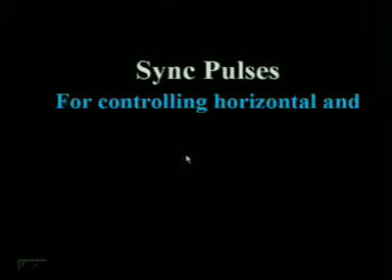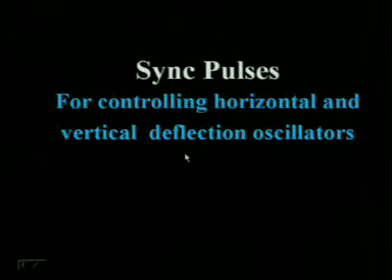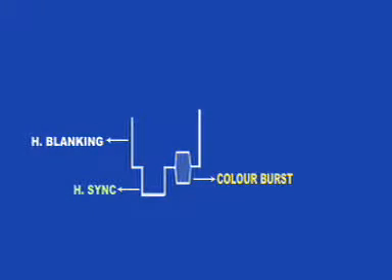Let us see here the sync pulse. Sync pulses are to control the horizontal and vertical oscillators. The sync pulses are first separated, then sent to the corresponding horizontal and vertical oscillator. How is this sync pulse separated?